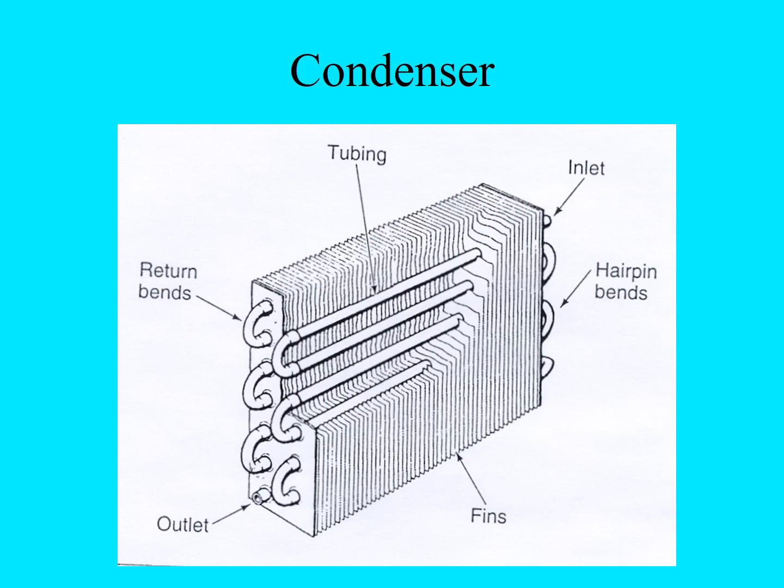So that's the purpose of the condenser. Now, the condenser could be mounted to the radiator through some mounts, or it could sit on its own rubber mounts in front of the radiator. So sometimes you might have to remove both to get the condenser out of the vehicle.